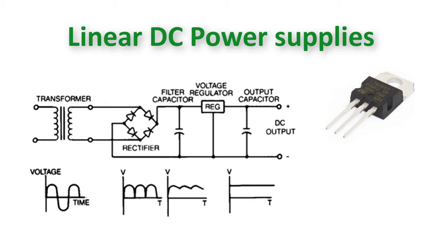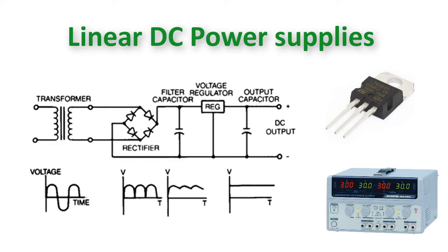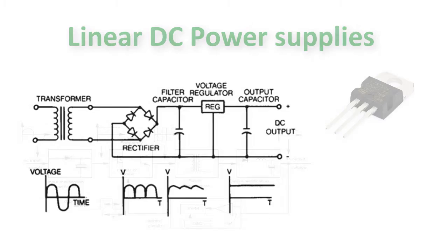Linear power supplies use a large transformer for the transformation of high AC voltage to low AC voltage. Next steps after transformation are rectifier circuits and different filters that create low-wave DC voltage. Low one-way voltage is then regulated to the given level with voltage stabilizers. The typical applications of linear power supply systems are audio technology, studio mixers, low-noise amplifiers, signal processing, data gathering with ADC converters, closed-loop management, and precise laboratory equipment.